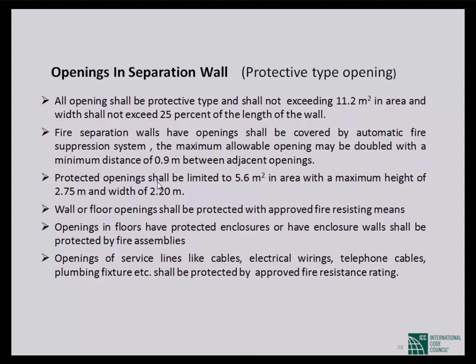Wall or floor. You can think, if it is a floor and there is an opening through the floor, it may be an opening for the stair. It may be an opening for the chute to move from one floor to another. You have to move electrical lines from floor to floor. You have to move plumbing pipes from floor to floor. So if you made some opening, you have to keep some fire resistant means.